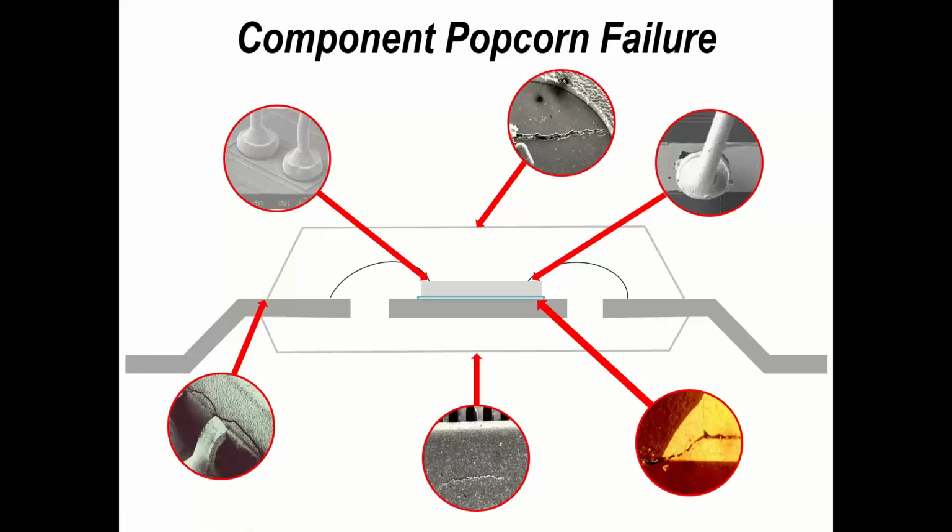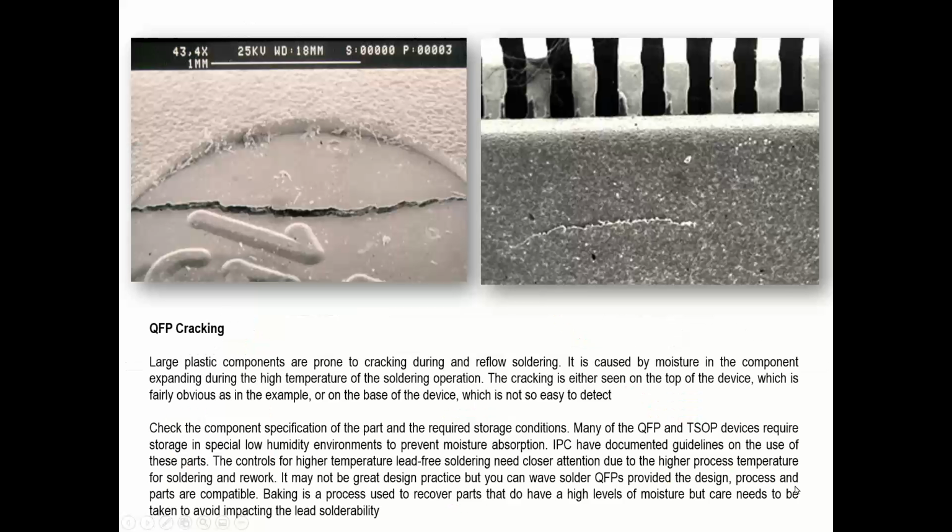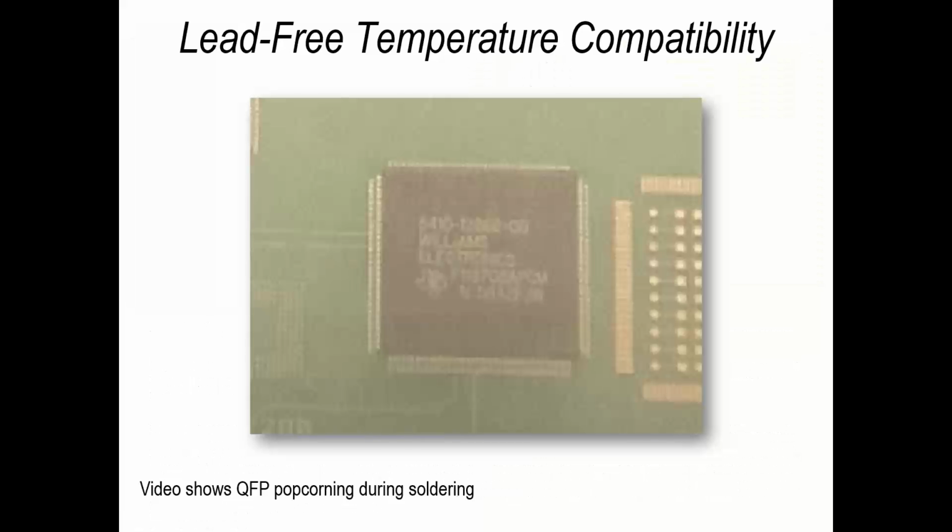You may not hear a pop, you may not see a crack, but you might see some discontinuity if you don't look after the packages prior to the assembly and soldering operation. And this is just a close-up view of 2 of the cracks that I showed you previously, and a little explanation of what cracking can occur. So that's what would happen. That's what you might see if you investigated.